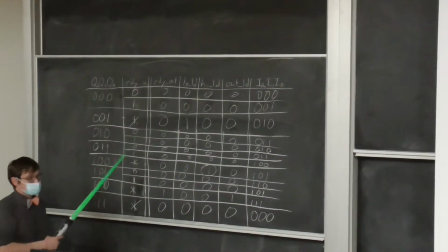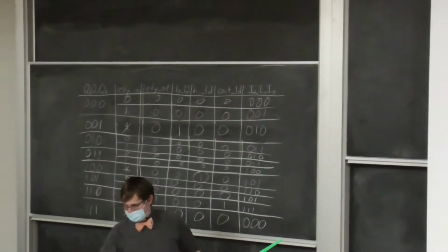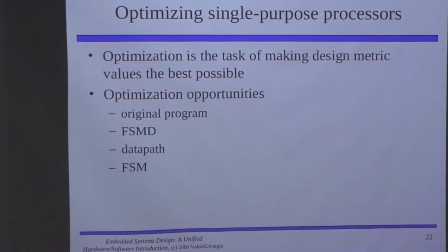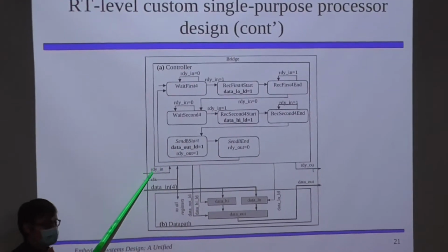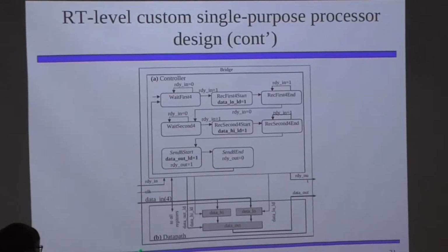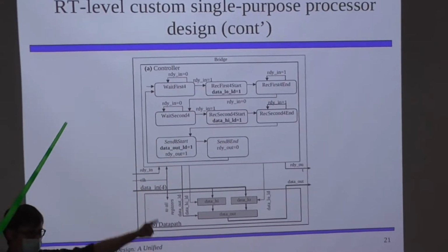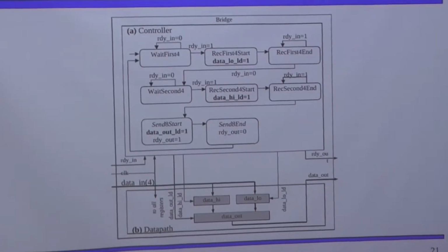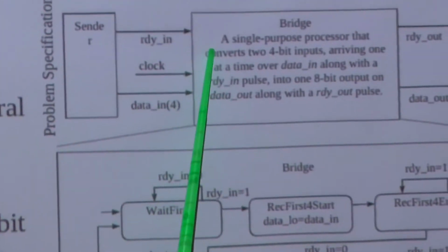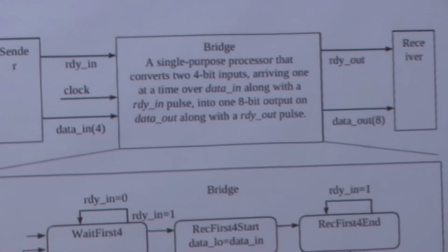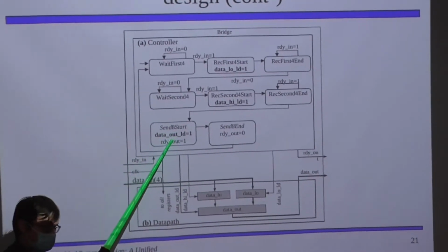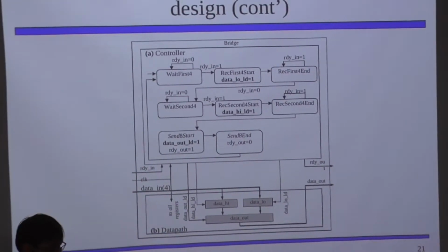This is the ready-in signal, which is coming into the control logic, right? So, where are we here? No, come on. Where are we? There we go. Okay. So the ready-in signal is a signal into the IC itself. So if we take this rectangle right here, that's the boundary of the entire controller that we're building, right? That's the same box as this box, right? So we've got the ready-in signal, we've got the data-in signal, right? So our design decision is to feed the ready-in signal directly into the control logic block rather than into the data path block. Are you with me so far?